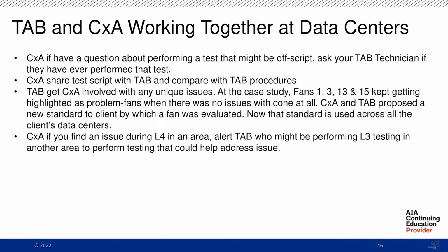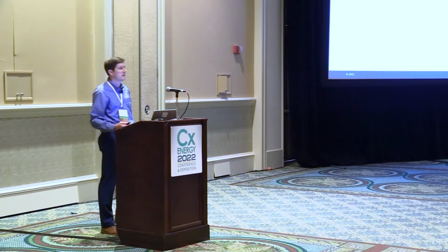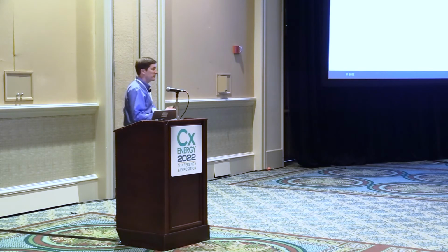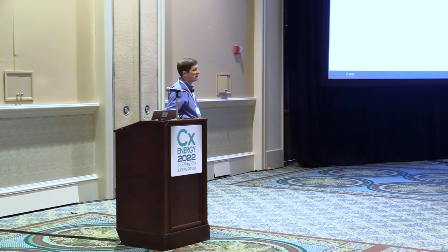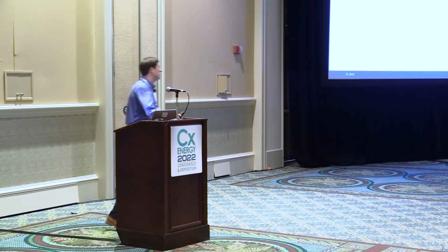All right, so TAB and CxA, what is a good way to work together? CxA, I would say if you have a question about performing a test that might be off script, talk to your TAB technician. Usually when I have a set of data there and it looks great, I've probably tested that equipment 3 or 4 times, just to see, is it working like it's supposed to?